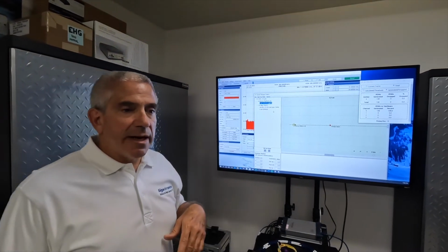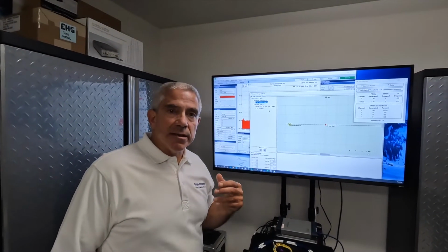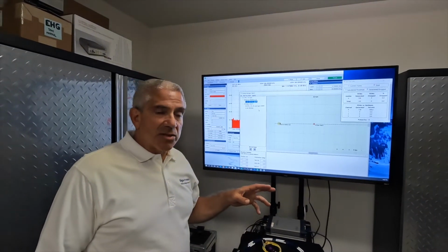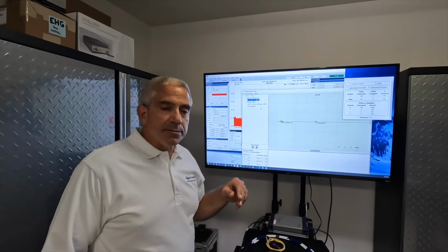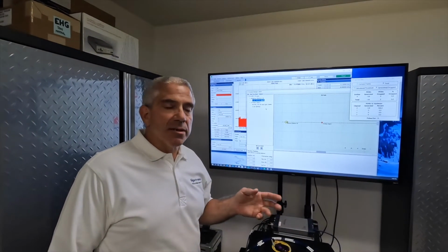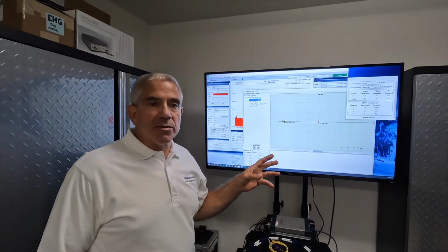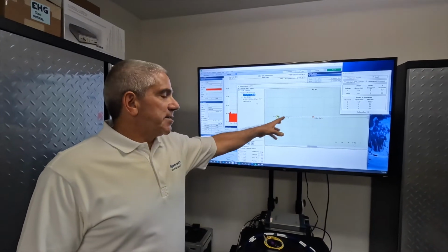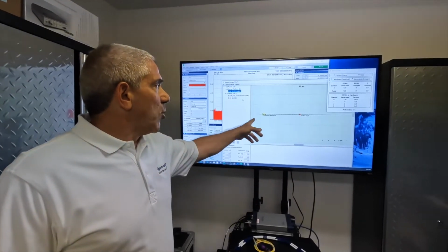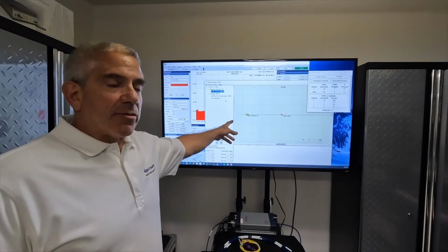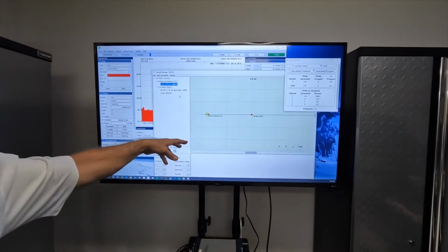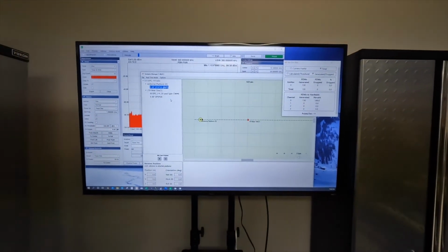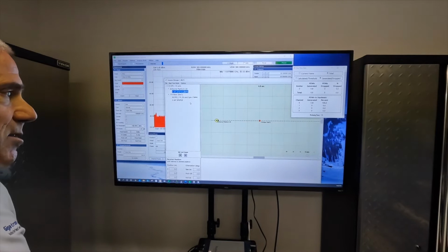First is the circular rotating scan pattern that we're going to simulate with this emitter, and also how the software handles what are called threshold drops. So it's actually going to be creating pulse descriptor words around the entire 360 degrees of rotation, but because the directional antenna on the emitter is not always pointed enough at the airborne platform flying into it, there's going to be a lot of times when the energy is below a set threshold, and we won't be occupying an available RF channel for a signal that's going to be too low for the system under test receiver to see it.